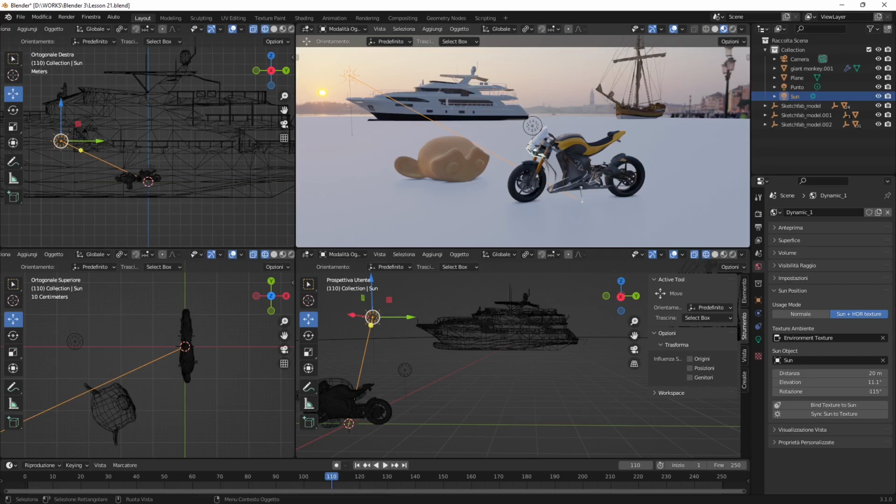So it's going to be a little bit better to improve the lighting a little bit, because materials actually react to light. You already know that HDRI is pretty good in terms of reflections and also generic and environmental lighting. But when we need a direct light source, it's better to have something like the sun or a point light to increase that materials effect.